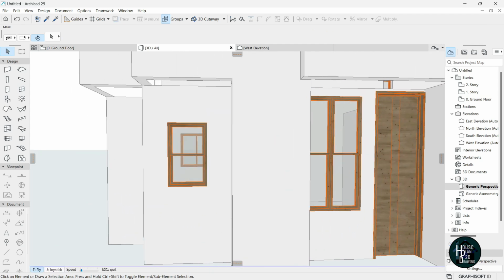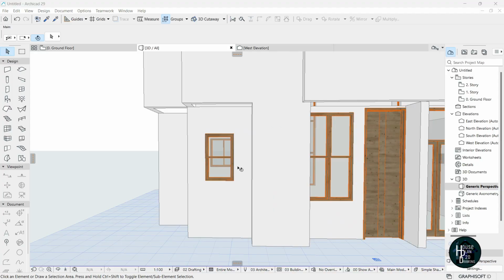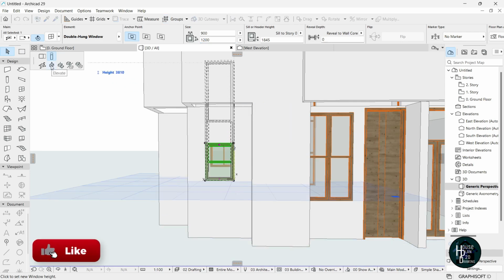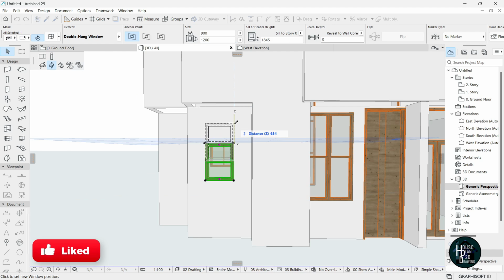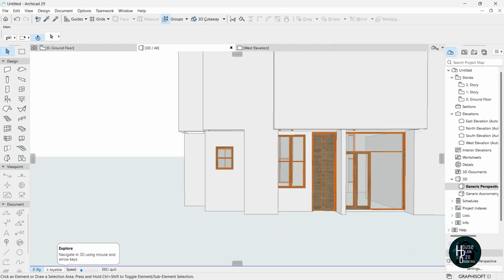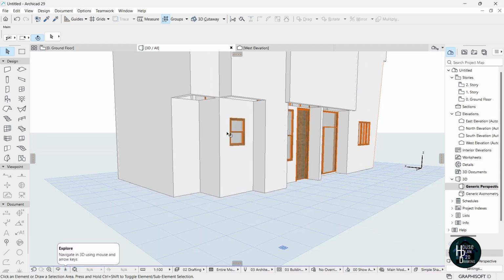So we just want to try and adjust this to conform with whatever thing that we want. Okay, so you can select this and change it to be 1 2 instead of 1 5. Click enter. Okay, so it's going to be short like this. You can click on the node here, and then we're going to be selecting the elevate and just elevate it a little bit like so. Okay, you can start to bring it down a little bit. Okay, like so.